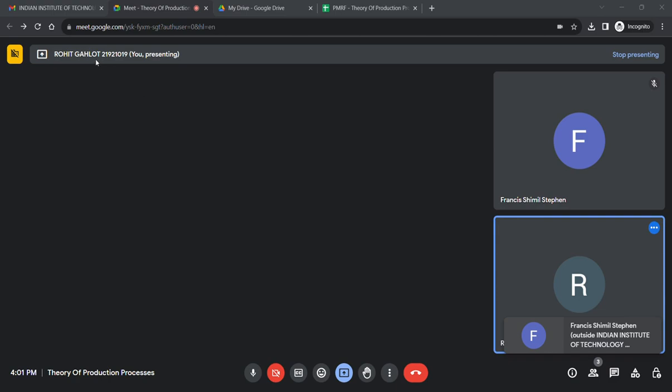So this V by A of the riser: as it is a cylindrical riser, right? Yes, sir. As it is written that it is cylindrical and also it is a side riser, and whose h is equal to d. So when you put these things in this formula for h equal to d, then your V by A ratio will come as D by 6 always.